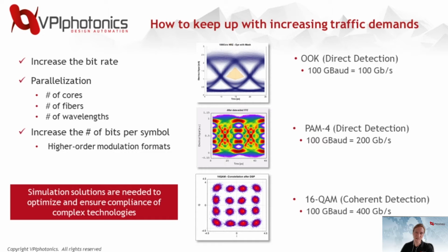And then lastly, we'll talk about QAM, or quadrature amplitude modulation, where we leverage now both phase and amplitude. And in the case of 16 QAM, we now basically have the option to transmit 4 different PAM4 signals, but each one corresponding to a different phase.